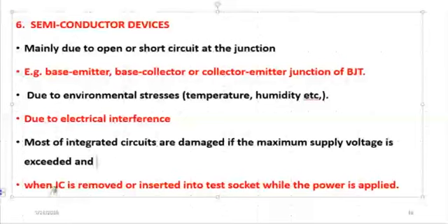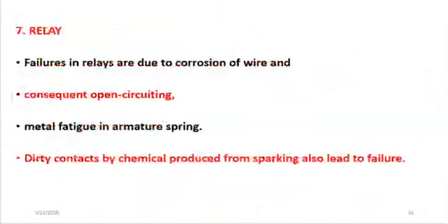Another problem that damages the ICs is removing them or inserting them in the circuit when the power supply is applied. Before you insert it, you have to remove your source of power. Before you remove it, you have to remove your source of power. If not, a failure will happen.